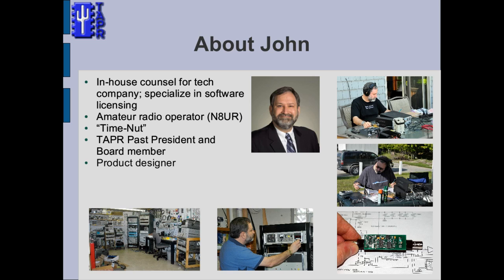Most of what I've done has been time and frequency related, but I've done a couple of ham radio projects as well. The picture in the lower right hand corner is a frequency divider based on a PIC chip that takes the input at 1, 5, 10 megahertz, for example, from a frequency standard and outputs a 1 pulse per second signal. I designed this board, and through TAPR we're making it available to the community.